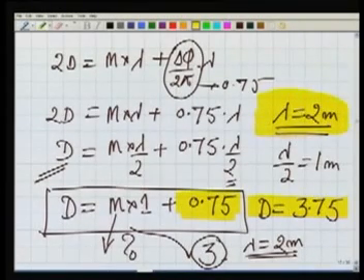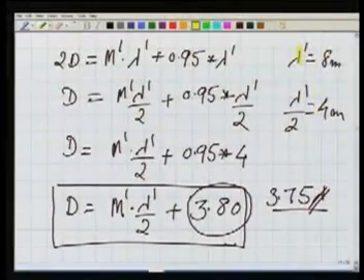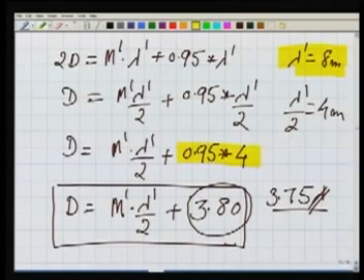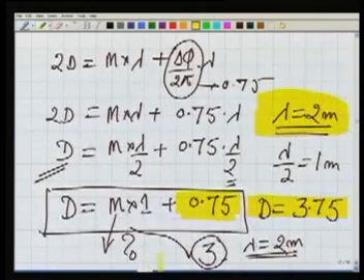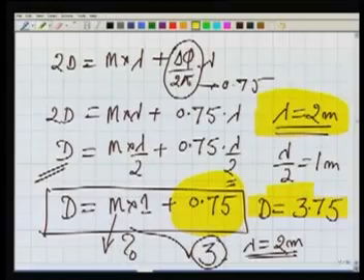So the part which is being measured by the phase difference is more precise rather than in the case when the lambda dash is 8 meters. In the case of the lambda dash, this particular part which is being measured by the phase difference is less precise, and because of this reason we are not taking the 8.0, rather we are taking this 0.75 from here, and we are saying our distance is 3.75. Now one more thing to explain this.